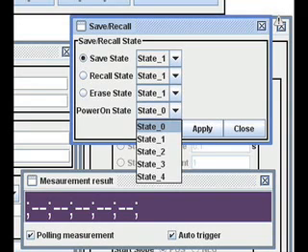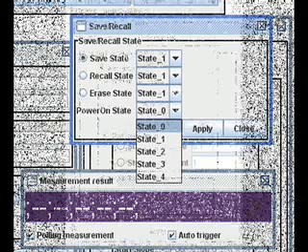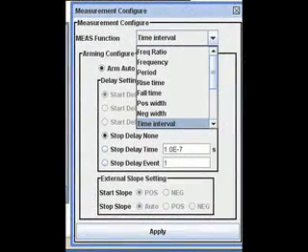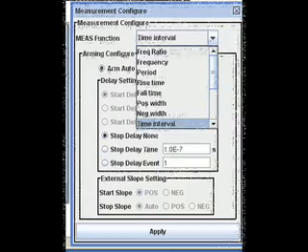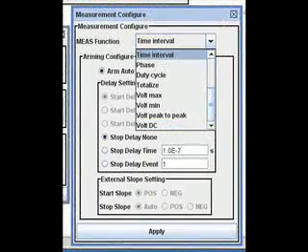Save and recall allows you to save and recall your measurement settings in non-volatile memory. Up to 20 different complete settings may be stored. SCPI commands are an ASCII-based instrument command language designed for test and measurement instruments. SCPI includes standard command sets for several classes of instruments. A predecessor of SCPI, but with more limited scope, was IEEE 488. See the manual for the 1105 for more SCPI commands.